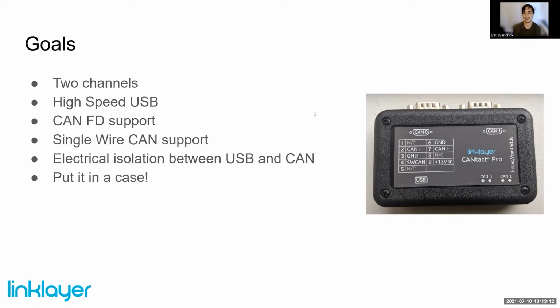But it also allows for a higher bit rate to happen during the data phase, which essentially allows for a higher throughput overall. So instead of being capped at 1 megabit with traditional CAN, you can go up to 10 megabits in that data phase and push a lot more data through in the same amount of time. Then also the 64 bytes lets you actually start to do things like data signing, or at least doing message authentication codes, because you have enough space to actually put a counter and a MAC value in there.